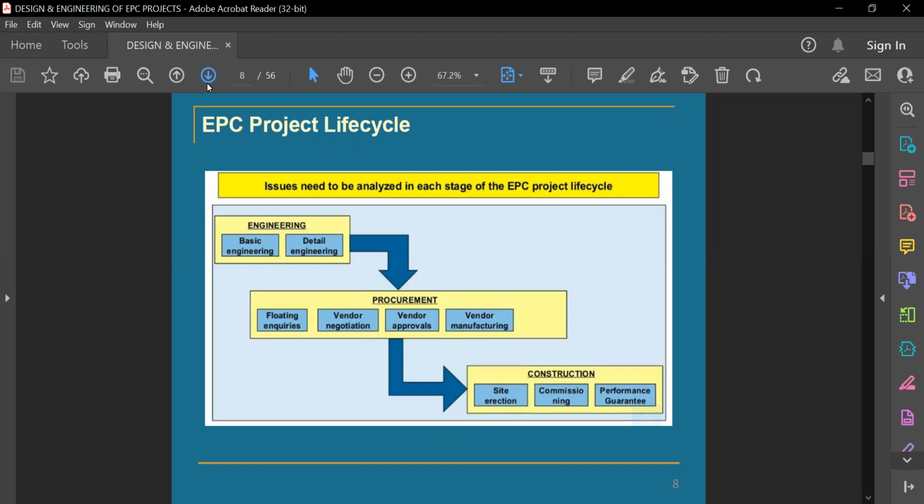So in the detail engineering phase, once the contractor is given the order only for detail engineering, he has to carry out further work. The basic preliminary plot plan will be with them, and then they will have the basic index, instrument index, for example the PNID, process flow diagram, some basic civil MTO, and piping MTO, material takeoff. On all the lists, broadly it will be there, but not in detail. Once they do the detail, they will have to recheck those things, correct them, and then make it in detail engineering.